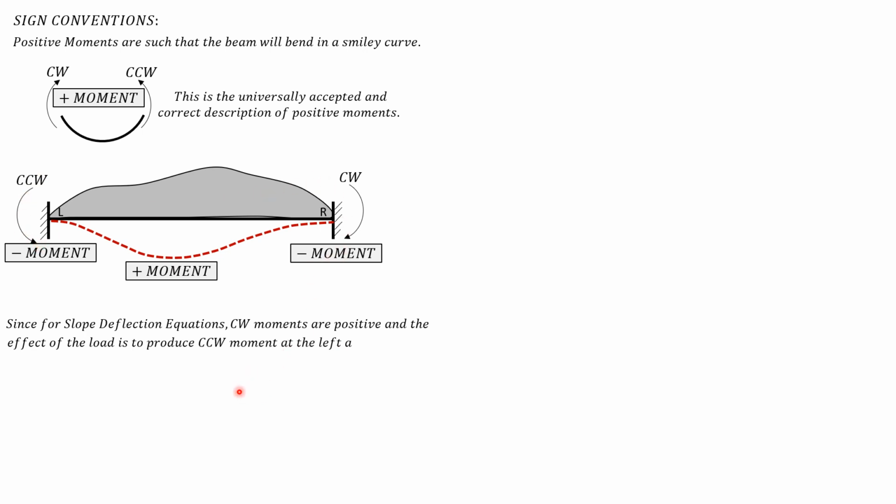Since for slope deflection equations clockwise moments are positive, and the effect of the load is to produce counterclockwise moment at the left and clockwise moment at the right, the fixed end moment L is negative.